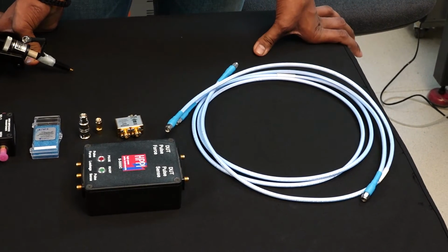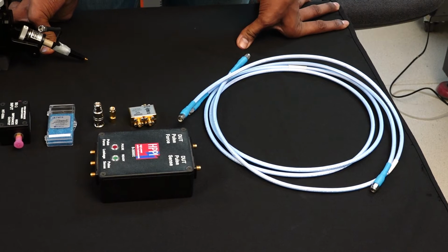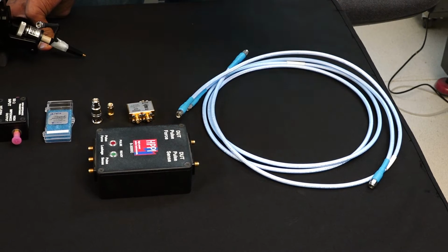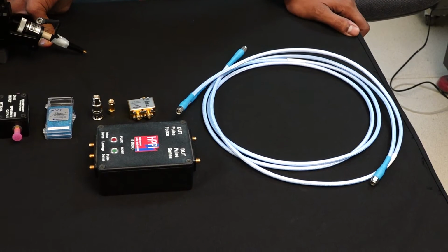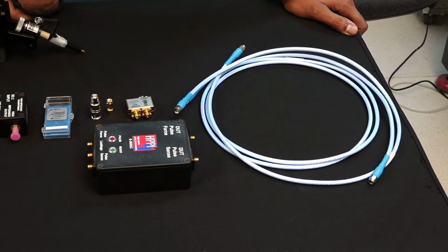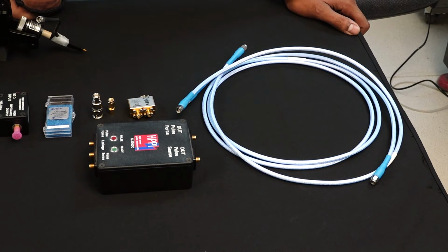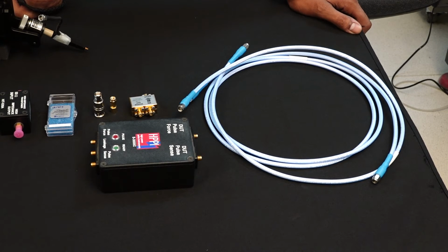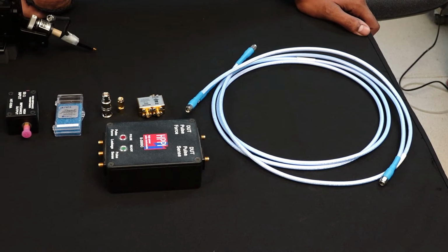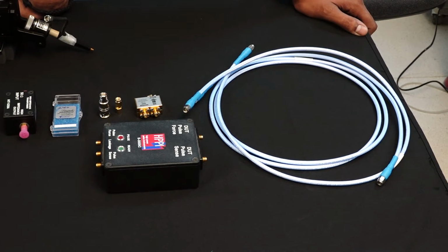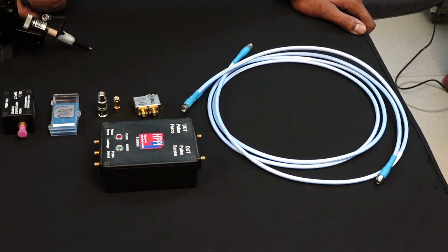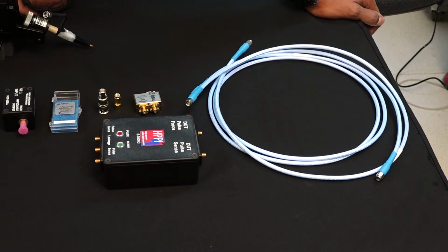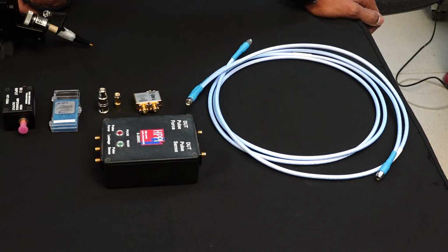Now you can see that I've kept all the transmission lines here in a circular fashion. The reason is you don't want kinks or any damage to the transmission line anywhere. If you remember your concept of transmission lines, the RC components of a transmission line are distributed in nature. However, if there was a kink or a geometrical damage somewhere in the transmission line, the distributed resistance and capacitance at that point of the cable would become different from 50 ohm, and that point would start reflecting different waves and you would not be able to measure the whole signal properly. So that's why it's very important to keep these transmission lines in a proper fashion and avoid any kind of geometrical damage to them.